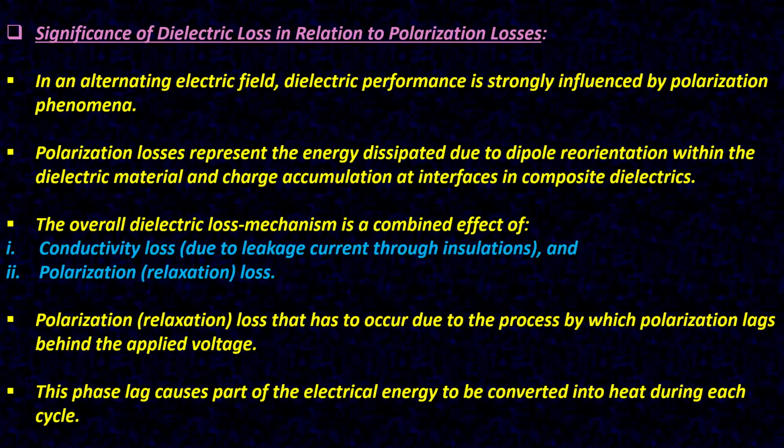The overall dielectric loss mechanism is a combined effect of one, conductivity loss due to leakage current through insulation, and two, polarization or relaxation loss, the relaxation of dipoles.